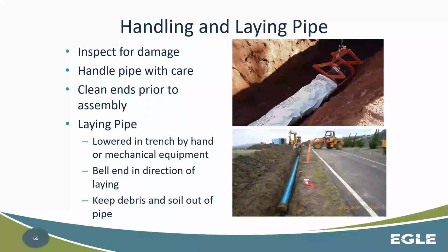And then keeping debris and soil out of the pipe. That means capping that end at the end of the day or whatever in some fashion, or just going through it as you're doing that process in general, making sure that you're maintaining a clean, fairly dirt-free installation. Because as I'm sure we have all experienced at some point in time, you don't want to have continued bacteriological issues.